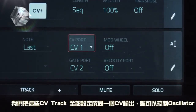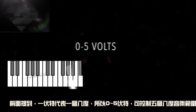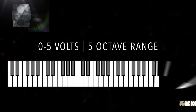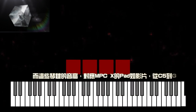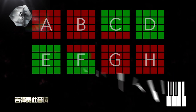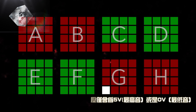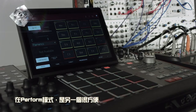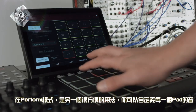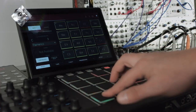Here I have the CV port configured to output 1. It is controlling the pitch of my oscillator. Again, the CV is 0 to 5 volts, so we'll get 5 octaves of precise tracking. On the MPC X hardware, the usable notes correspond to pads C5 through G1. Notes played outside of the 5-octave range are rounded to either the highest or the lowest available notes. Pad perform mode is another great way to use the pads to jam with predefined scales.